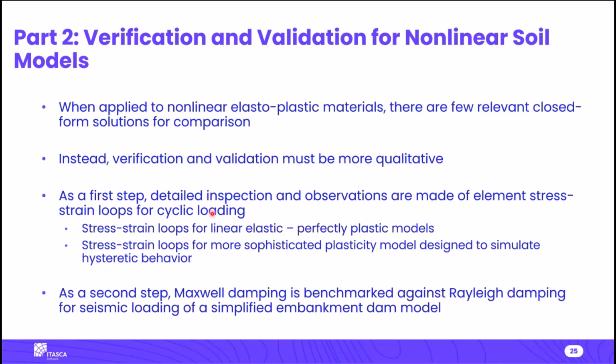As a first step, we did some detailed inspection and observations on stress strain loops for linear elastic perfectly plastic models and for more sophisticated hysteretic type models. And as a second step, we did a sort of benchmarking analysis between Maxwell damping and Rayleigh damping for seismic loading of a simplified embankment model.